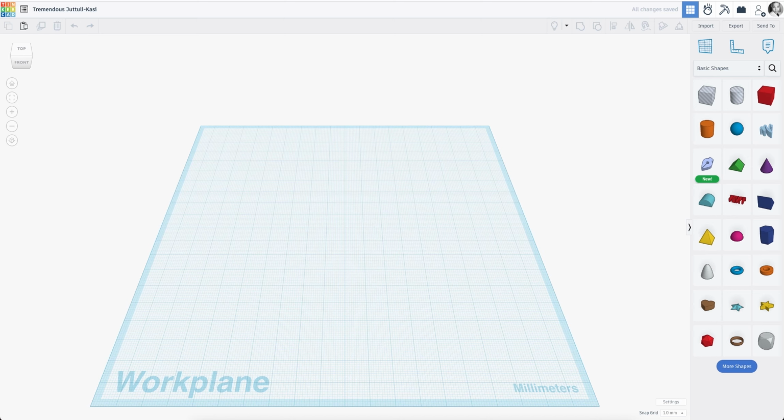Now we're going to start first of all by using the slice tool. Now what is the slice tool? The slice tool is usually used if you have a large product. So let's say, for example, my product exceeds the space of my 3D printer. In this case, I cannot print all of it at once. So what I have to do is cut my product into parts after finishing the product. And in this case, I can print it on a small scale 3D printer.